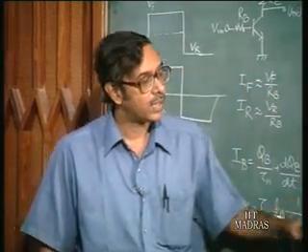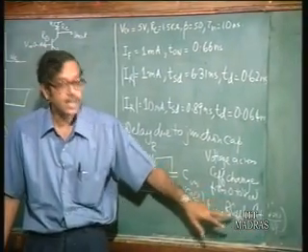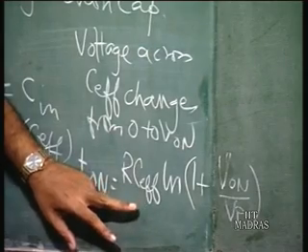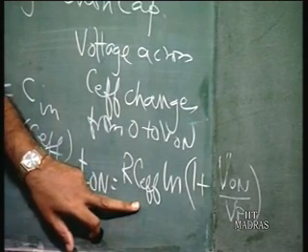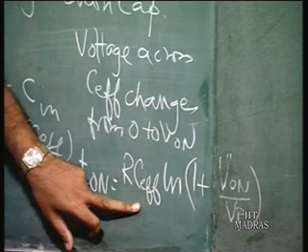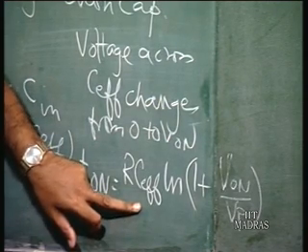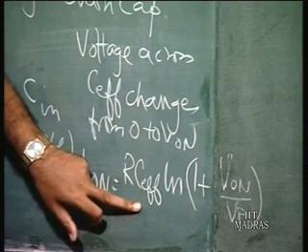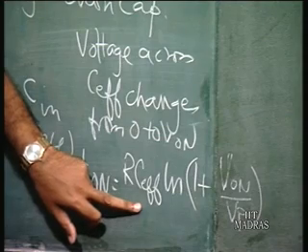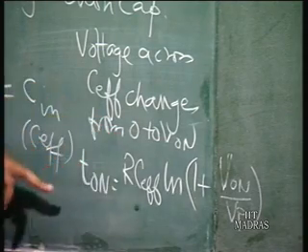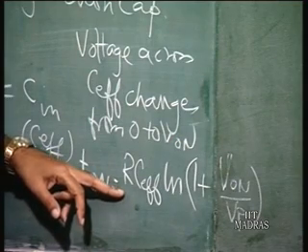Okay. But if you look at the junction capacitance expressions, the on-delay is RC effective, and C is independent of the currents. So, if you increase R, the delay is going to increase. All right. So, these are the two basic differences in the nature of the two delays. Suppose the resistance values in the circuit are very high. What is going to happen? The delay due to the junction capacitance is going to dominate.